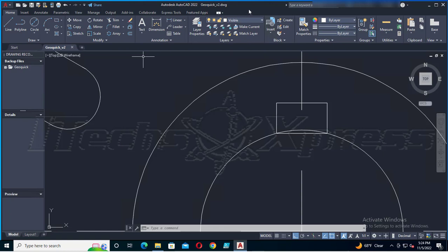Alright, so we're coming to the home stretch. First thing I need to do is explode this rectangle. So to do that, I'm going to click on this and press enter. So now I believe it becomes instead of one thing, yeah, we've broken it up to other things.